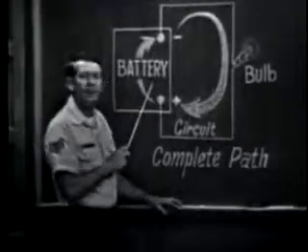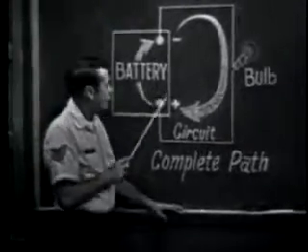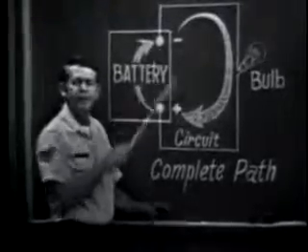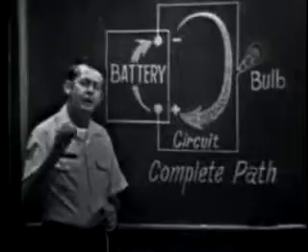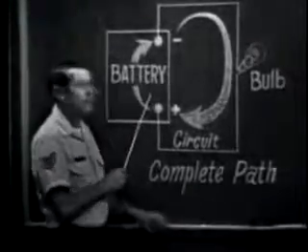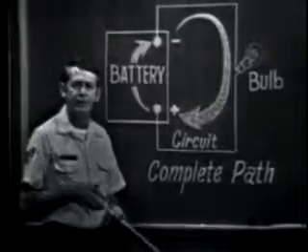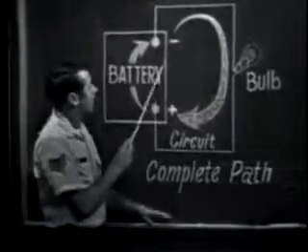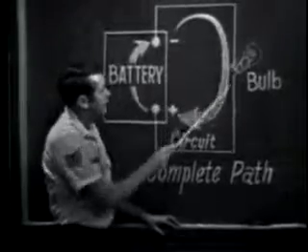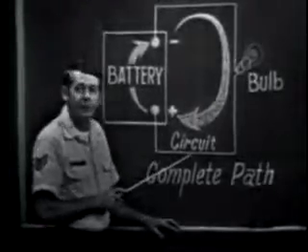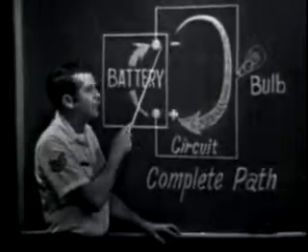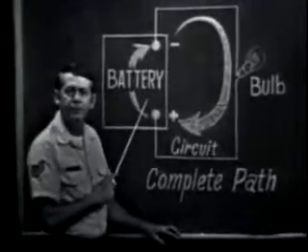Inside the power source, the battery in this case, current flows from positive to negative. Now, this is a very important point, so be sure that you understand it, because later on you'll be using the current in this power source to calculate numerous things. So remember this. Current flows in a continuous path from negative to positive in the external circuit, and from positive to negative in the power source.